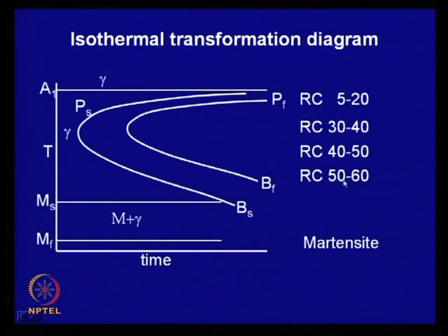Whereas in this particular case the carbides are still finer and the shape of the ferrite grain where this carbide precipitates is a little needle like type of structure.